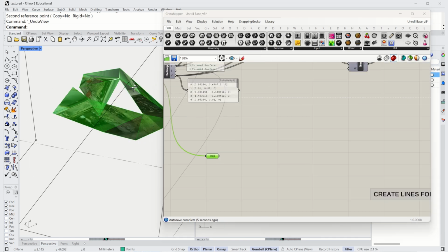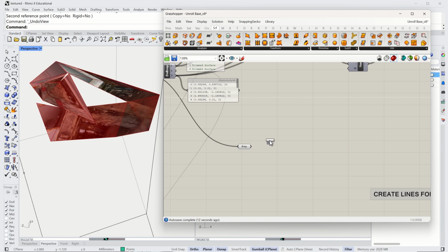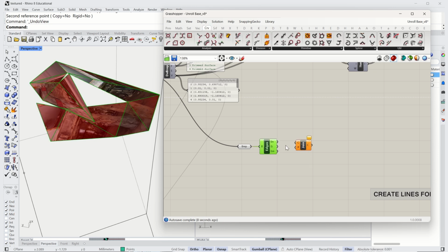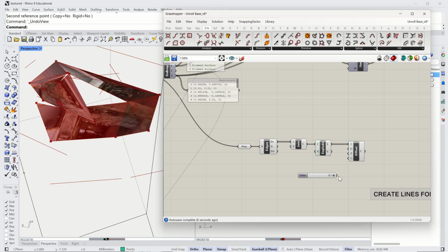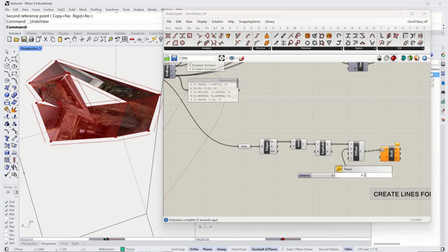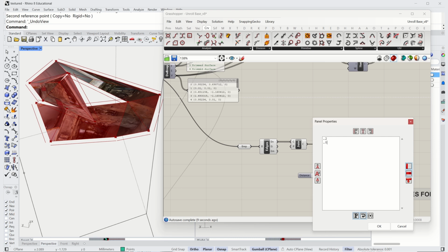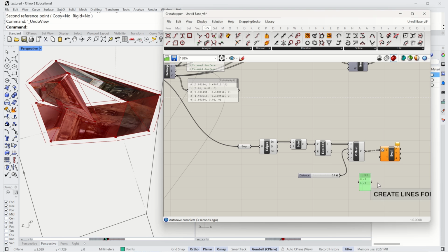To add tabs for building a physical model, we take the outer edges, join, and then explode to ensure they are all facing the same direction. Then offset the width of the tab. Evaluate these curves at 2 points, just after the start and before the end, and merge these with the original curve's start and end points to make a chamfered corner.